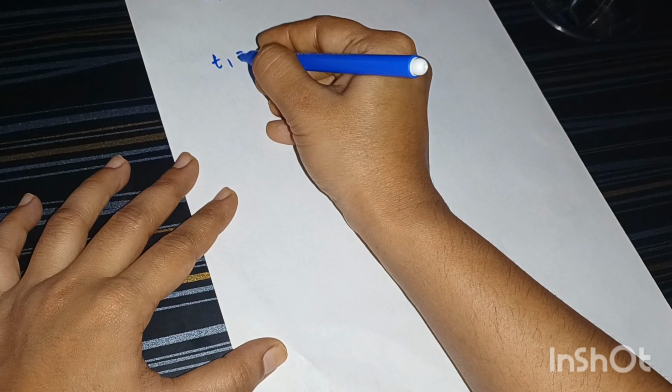For a similar circuit, when the capacitor keeps on charging, it will keep on staying at the UTP level. When the capacitor starts discharging and reaches 0, it will go to the lower triggering point. It fully discharges and goes to the lower triggering point. When the capacitor is again charging, it will start increasing till it reaches the 0 point. Once it crosses this 0 point, it will charge and go to the UTP level.